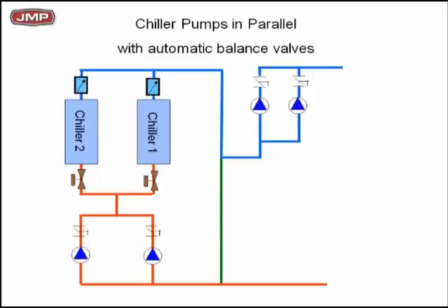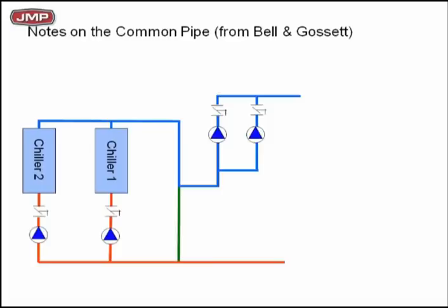You see the green common pipe. You've got secondary pumps. But if you've got a pipe this way and they're not dedicated pumps in a primary-secondary loop, you need to put 2-way isolation valves on each chiller as shown, and flow limiters on each chiller just to protect them. And that's another old seminar we can dig into deeper, but I'm just cautioning you, if you want to pipe them this way, great. Just make sure you have the 2-way isolation valves and you have the flow limiter.